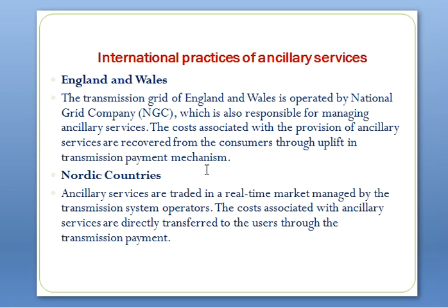The provision of this service is required from all the generation units with a capacity over 30 megawatts. Voltage must be kept within the range of V nominal plus or minus 10% for the 400, 275 and 132 kilovolt networks, and the power factor between 0.85 capacitive and 0.95 inductive. The main costs associated with this service correspond to the capacity and operation.